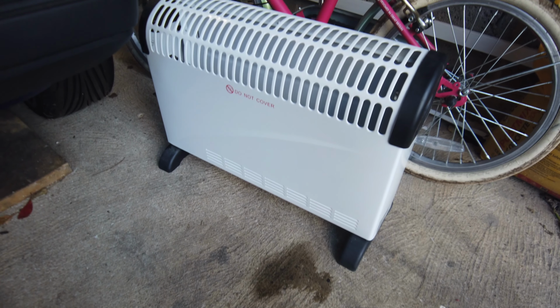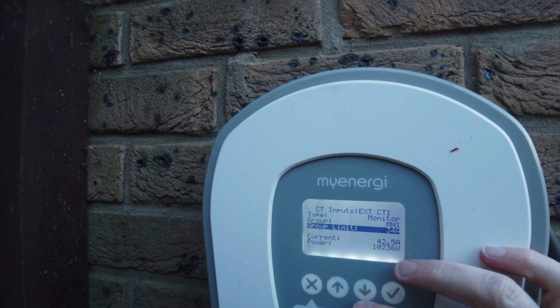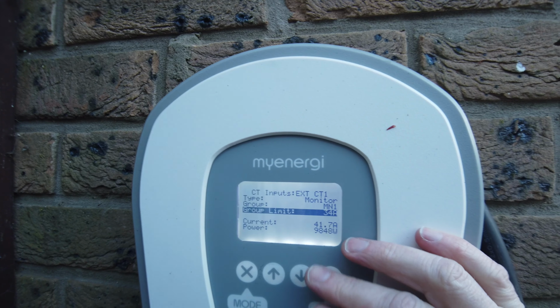When I actually went to test this, I was doing another video to follow up on the video I did last week to actually test the monitor mode, and I got some stuff. I got a 2 kilowatt heater out here. I set the monitor mode down to a lower threshold to see if it would cut in and start reducing the load, and nothing happened. It drew 10 kilowatts absolutely fine, and it was way over what I'd set. So I thought, what's going on there?